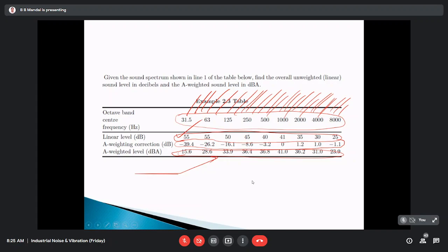Outside that, ultrasound or infrasound, we are not interested. So these filters will only filter out the top portion and bottom portion beyond the sonic range. The infrasonic part and the ultrasonic part will be completely eliminated. The rest is heavily attenuated, which will not create any difference in the final output.